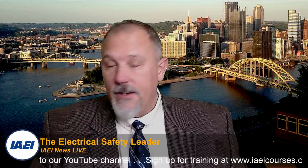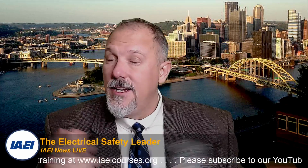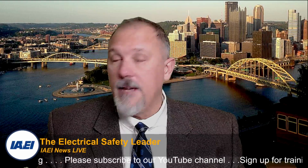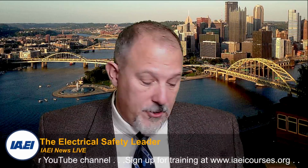Now, I don't care if you're using a GFCI receptacle or a circuit breaker. You'll notice those GFCI circuit breakers, most of them have pigtails, but beware, some of them do not have pigtails. They call those a plug-on neutral application type of device, and make sure you understand the way those go into the panel board from the manufacturer.